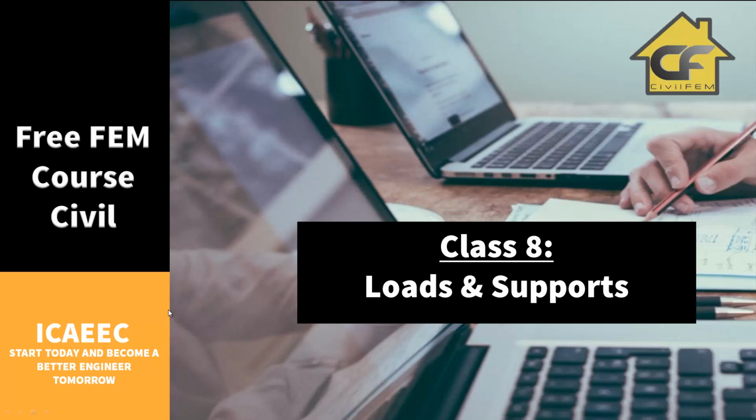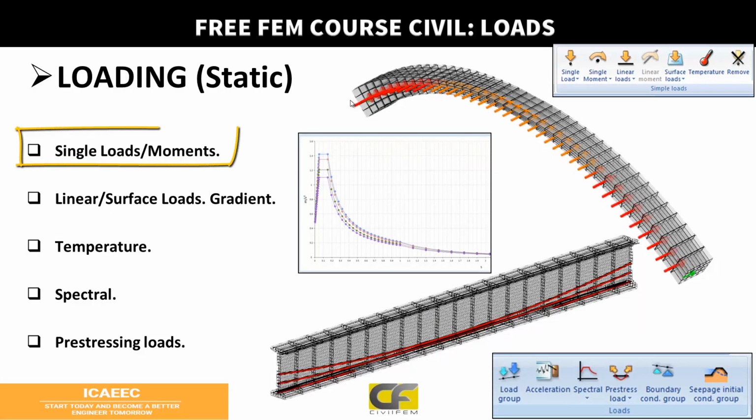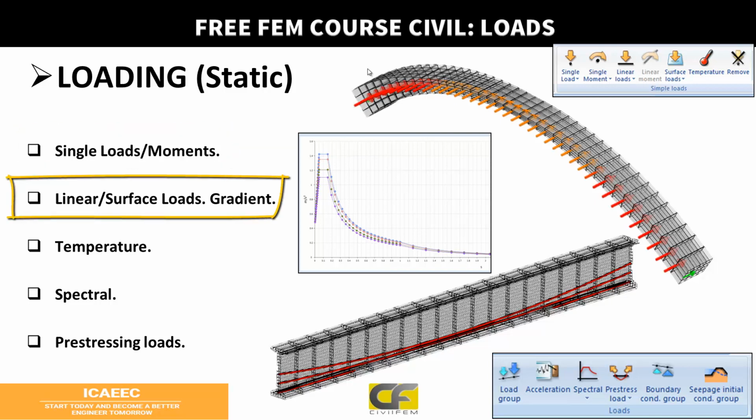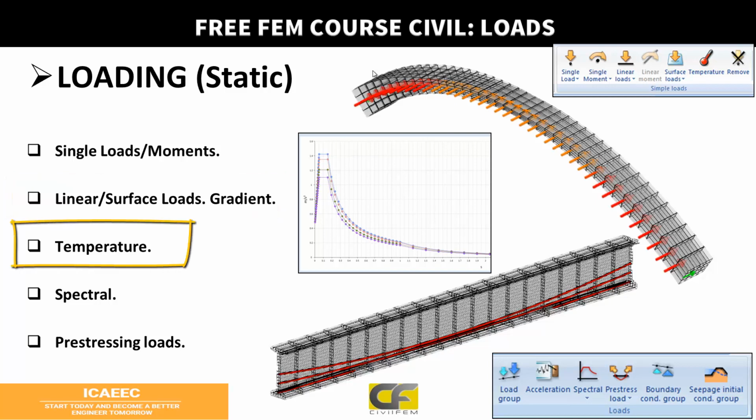Today we will talk about loading and setting the supports for the boundary conditions. They are important for a correct analysis, because usually we do not set boundary conditions correctly, so we might have incorrect results. Typical loads: single point loads, moments, linear and surface loads including gradient, and temperature, structural temperature, because heat transfer is included in another field. You can even couple the heat transfer to the structural analysis.